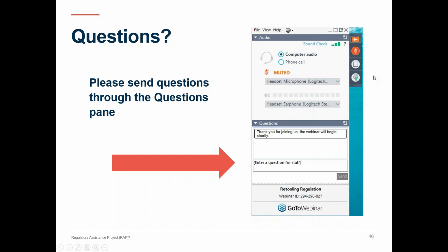Now, you usually want to charge the same time of use periods for the whole class, rather than getting into people in one neighborhood having a rate whose peak hours end at 6 p.m. and another one whose peak hours go until 9 p.m. That's going to be a really confusing rate design to communicate. So for rate design, you often have to aggregate. But for cost of service purposes, you can look at how each substation and each feeder is peaking and use that information. Jim, you want to say something?